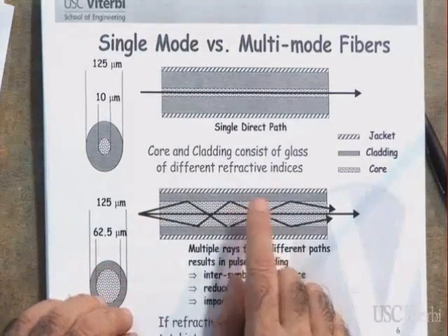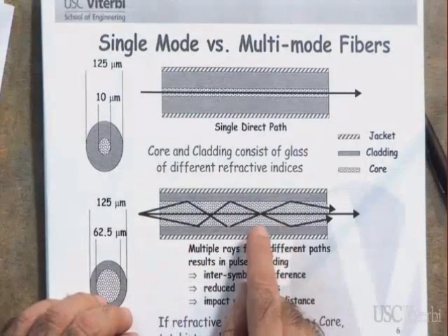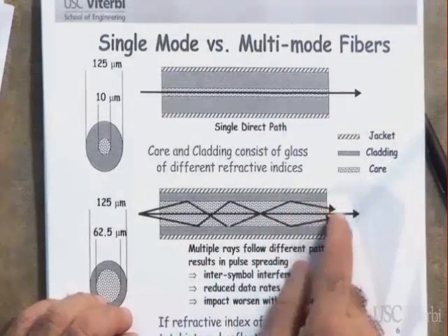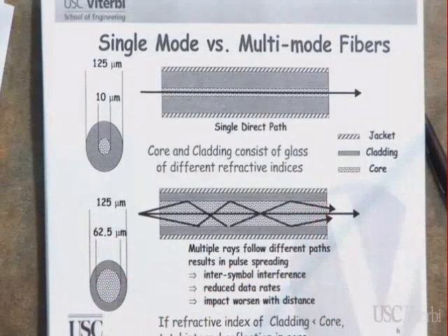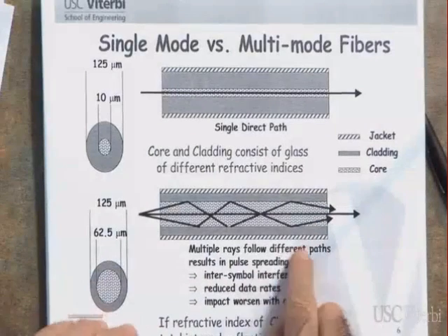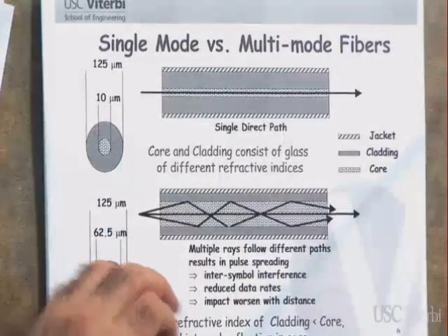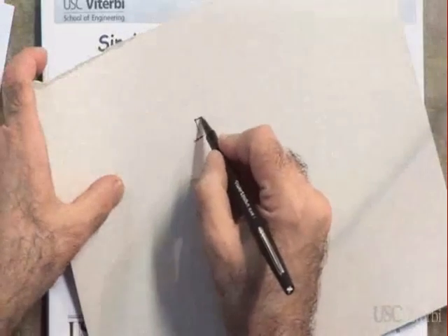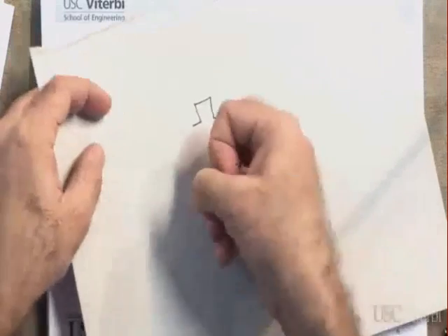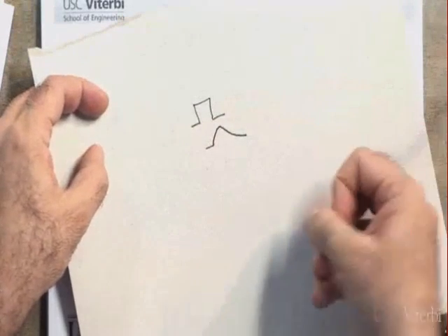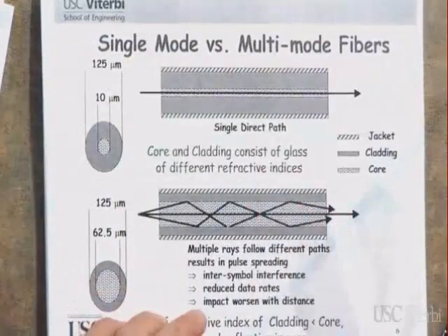Now, in this case, what you are going to suffer is in the pulse. If you take the sum of these, you will see that the pulse will become a little bit smeared. It becomes spread. In other words, instead of the pulse like this, it will become like this a little bit. It gets stretched and attenuated because of this multipath.